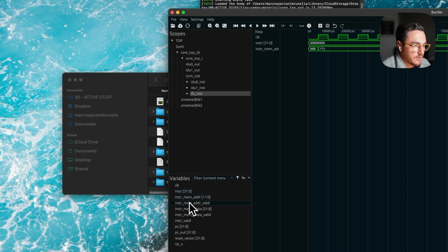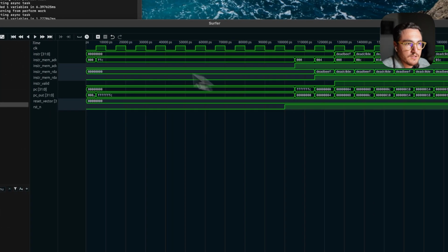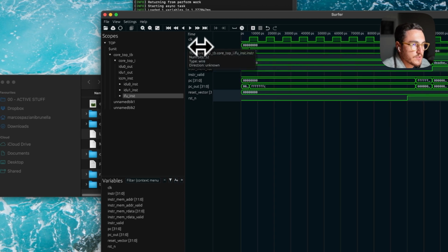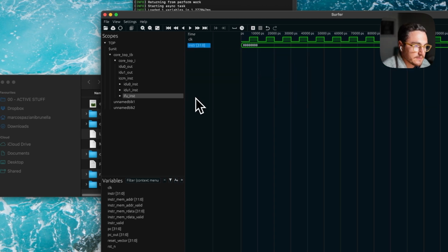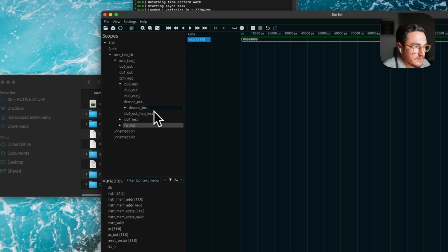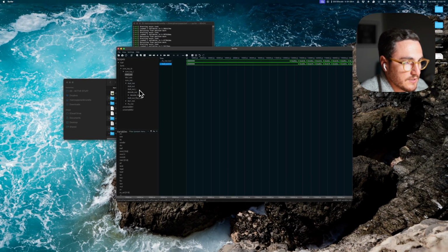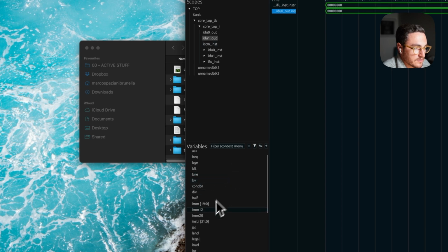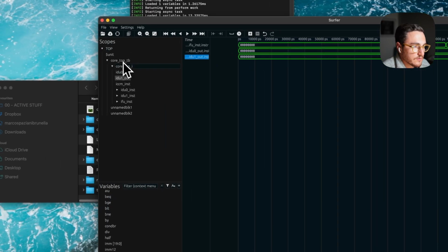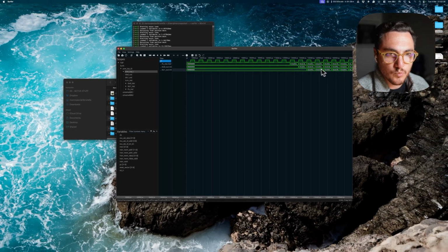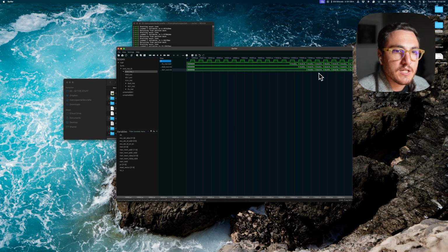Again, here you can just click on things and you see all the signals that are going on inside our design. One thing that we can do is make sure that the instructions are flowing down the pipe correctly. So this is the instruction in the fetch stage. Let's go and take a look at the instruction on decode stage 0 and on decode stage 1. And you can see that they are all spaced by 1 clock cycle. So the pipe is working correctly, and you can see that once the pipeline is full, we have one instruction going in and going out for each clock cycle.